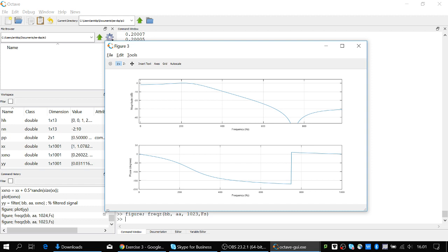So the system actually has the 3 dB point around 260 hertz or so. Oh, actually, I don't know. This is more like 300 and something. About 330 hertz, 3 dB point. So basically, all the noise which is here hasn't been attenuated at all. Okay, so it cut only, say, higher spectral components. Good.